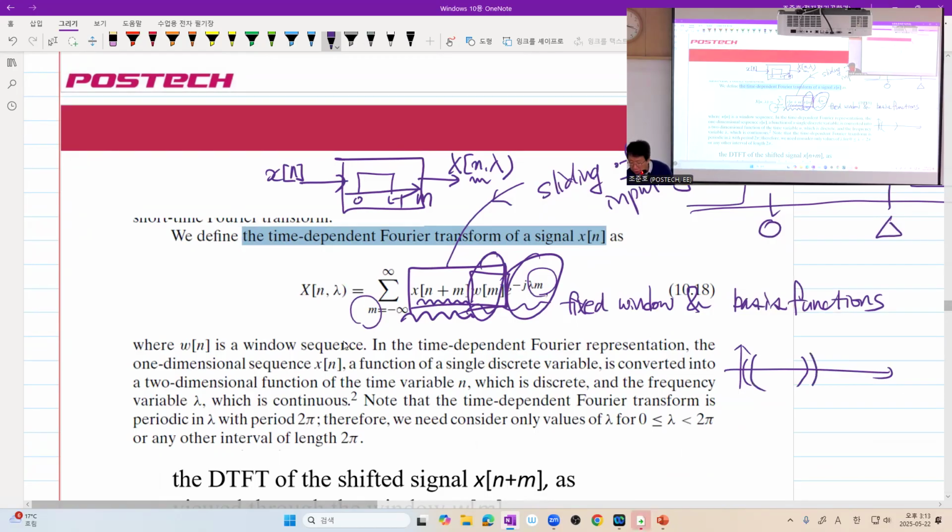I take that part, Fourier analysis, that part, DTFT, that part, something like that. Because usually after computing this one, which is in general a complex value, we take what? 20 log absolute value of this one. So anyway, phase information will be gone. So sliding the window is the same as advancing the signal.